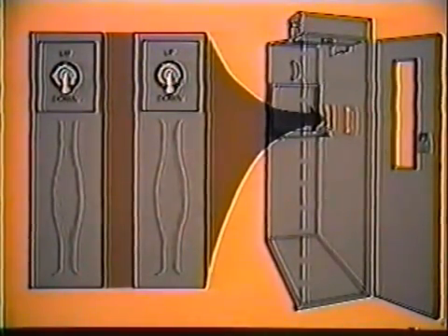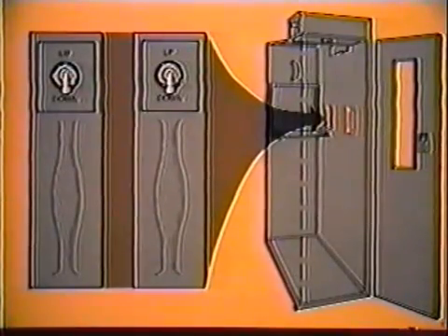To operate the lift from the inside of the lift, make sure the lift door is shut and latched. Place both hands, one on each assist handle. Place thumbs on the toggle switches above each handle and press and hold both switches simultaneously in the desired direction until the lift comes to a complete stop.